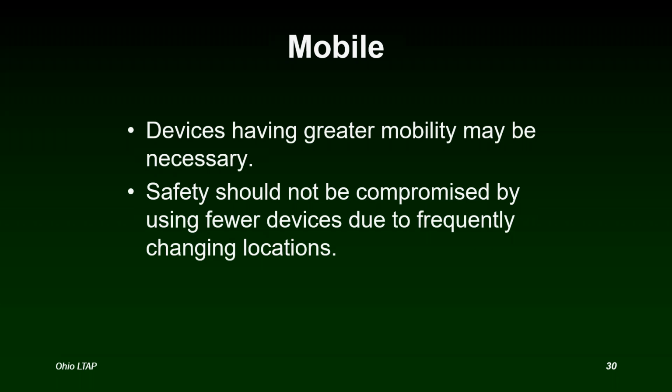And you also really need to consider your advance warning area. The thing about mobile operations is that you have more of a chance of surprising the motorists. So you really need to put some thought into how the motorists are going to see us out here in this mobile operation. So sometimes you need to add signs beforehand.